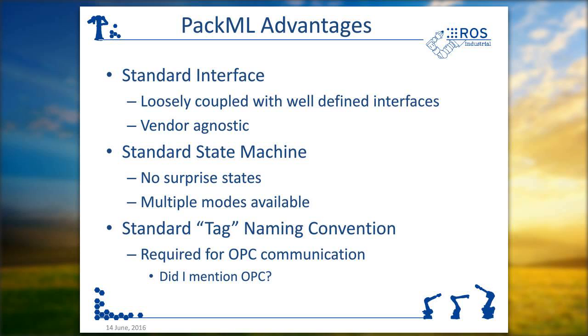It also has multiple modes. So the state machine that I showed you earlier, you can have layers and layers of those for various modes, where different programming models for setting up a line are in place with different operations. If you have a setup mode versus a maintenance mode, which might offer some interlock defeating or some other types of things that you might want to use for testing, versus an execute or a run mode that would just be a full production automation mode. There's also the ability to set up something for a local mode where it's not connected to anything else so that it can run on its own. All of these things are capable with this PackML standard.